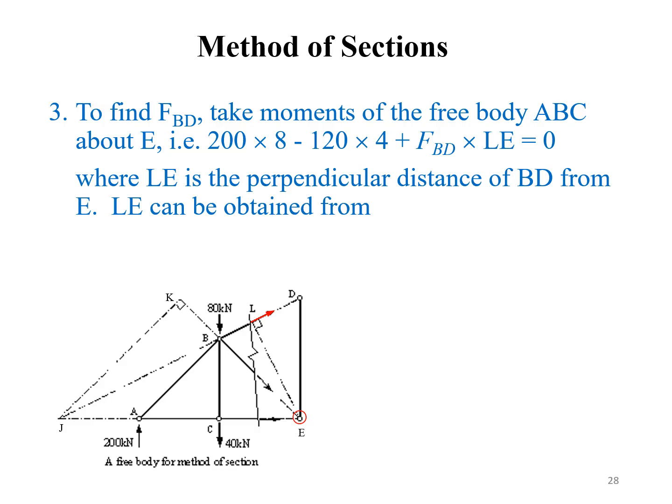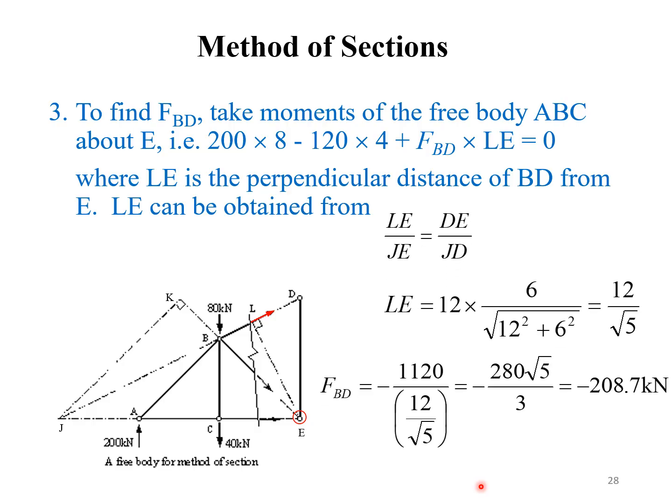Let's start with FBD. To find FBD, take moments of the free body ABC about E. Please see this equation, where LE is the perpendicular distance of BD from E. LE can be obtained from this equation. So FBD can be calculated.